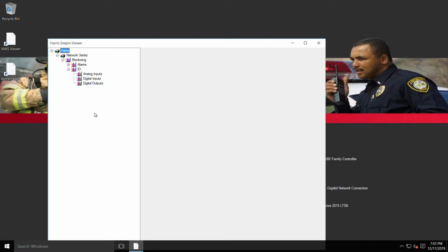Now, the multicoupler unit, or MCU, the ones they've shipped us only have a relay, a contact closure to give us an alarm. Therefore, those are a digital input. They're either open or closed. It's not an analog input that would be measuring a voltage or a current. There's been some confusion about that, so that's why I mention it.